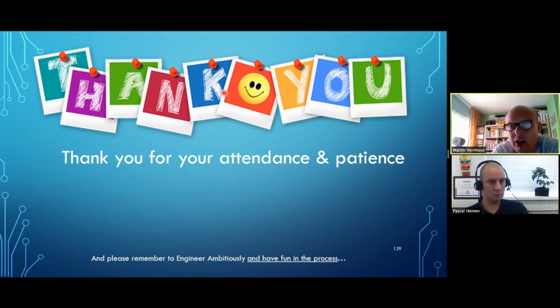The second one is, go to one of the boards from National, because that integrates nicely, of course, with the DAQmx driver, which saves you a lot of trouble getting it to work. Some of the boards from National might not be the cheapest, but the combination always is relatively optimal. You get good hardware, great support, and a driver which really works. Read the manual to see, can I connect my live signals in the right way? The next step would be the introductory talks about doing measurements with DAQmx for analog input voltages or currents. Do you need a filter?